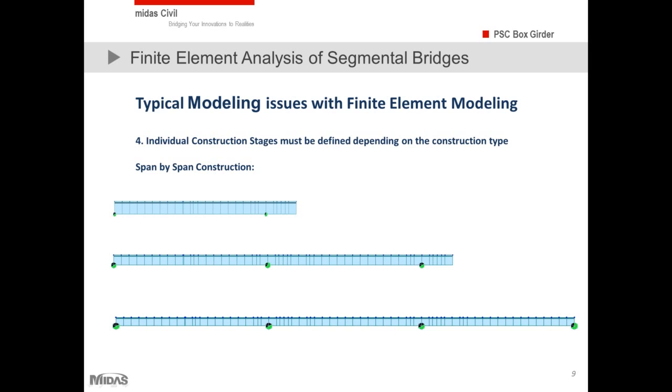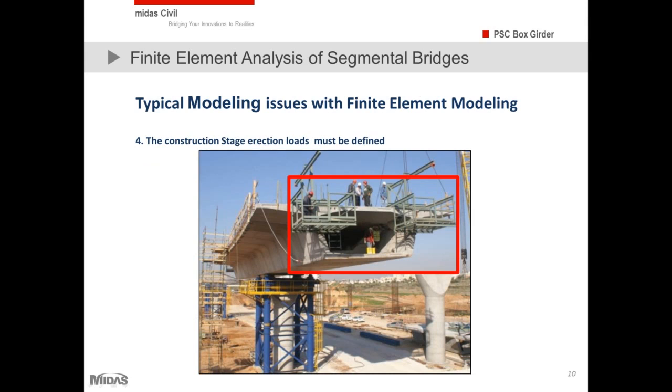So the idea behind telling you these types of construction methodologies is that in any software you are working with, you need to artificially simulate these construction stages so that you can obtain the precise effect in individual construction stages. The individual construction stages in the bridge should not be critical, and that's why we need to perform a staged construction analysis. At the same time, we need to obtain the camber for bridges constructed using the balanced cantilever approach, and that's why construction stage modeling is important.